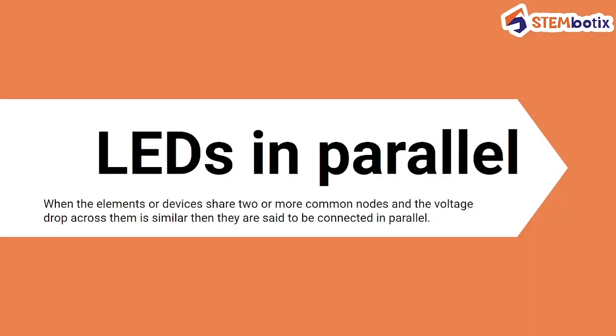Let's see LEDs in parallel. So what is a parallel connection? When the elements or devices share two or more common nodes and the voltage drop across them is similar. So in parallel they share more than two nodes, and the voltage across them is similar. While in a series connection, they share only one common node and the current flowing through each of the devices is similar. In the parallel connection, the voltage across them is similar, and then they are said to be connected in parallel.